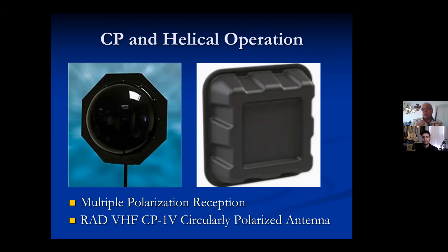If you split two Omni antennas, you're going to create a phase cancellation that wouldn't be there if you didn't split at all. Whenever I split antennas, A, I only do it with directional antennas, and B, I point them in opposite directions, so that the chances of one zone ever creating a multipath cancellation in the other antenna is zero. The cancellation will happen in the cable someplace in between. Because in the case of the helical, the front to back ratio is 30 dB. So you would have to have a 5-watt signal on one side of the antenna to step on a 200 milliwatt signal on the other side. So that's why I use directional antennas when I split, and I never point them in the exact same directions.